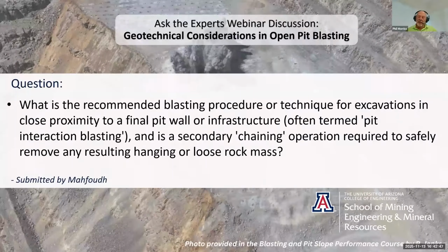So certainly, using equipment that's specifically designed for the task of bringing down any loose material, to avoid having to do any secondary blasting, is good. And obviously monitoring is something that we would expect you to be doing adjacent to any infrastructure, to ensure that you're not getting any far field or even near field vibration levels that exceed acceptable levels.